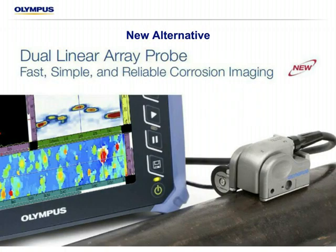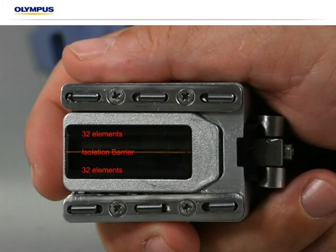Taking the best practice of conventional thickness gauging for the corrosion world, we developed a new dual linear array probe. As mentioned before, this one follows the common methodology of a V-path, or separate send and receive transducers.